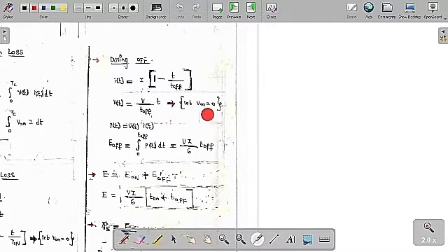I am going to assume the voltage drop in the on time is 0. So now we can see clearly power is the product of the voltage and current. But I want to know how much energy is lost in the off period, which is the integration from 0 to t of P(t) dt. So finally you are going to get Vi/6 into t off. So this much amount of energy is going to be lost in the period of t off.